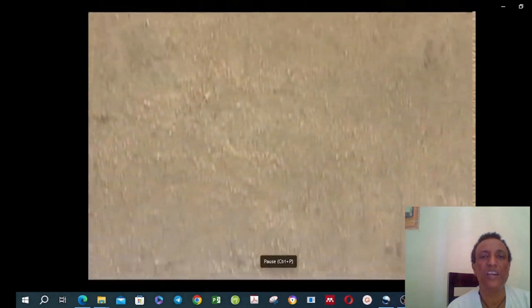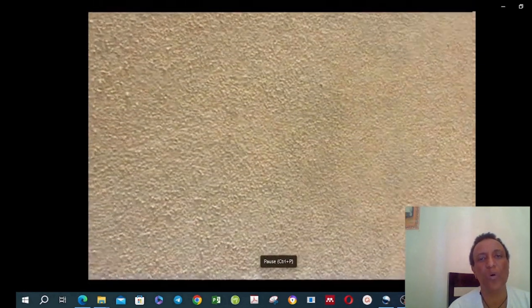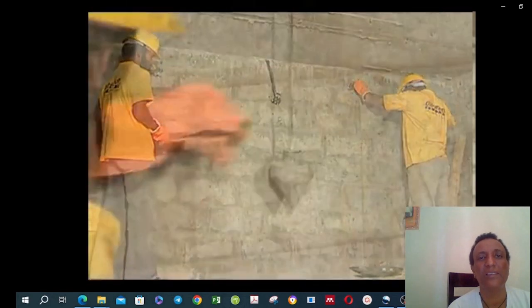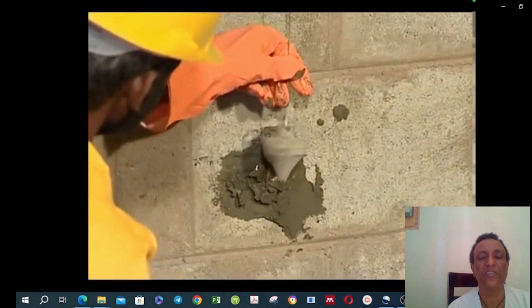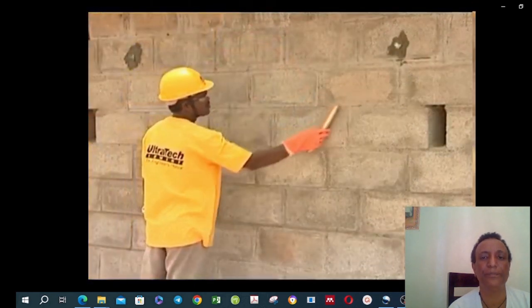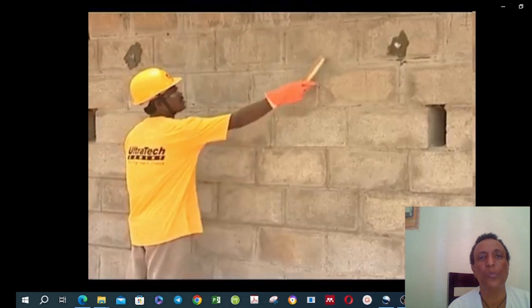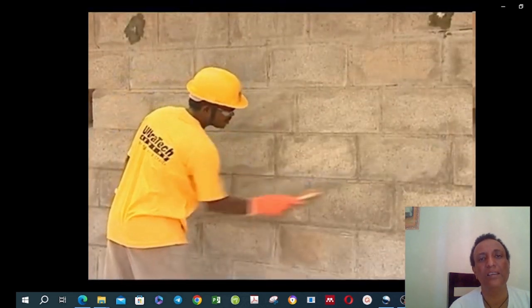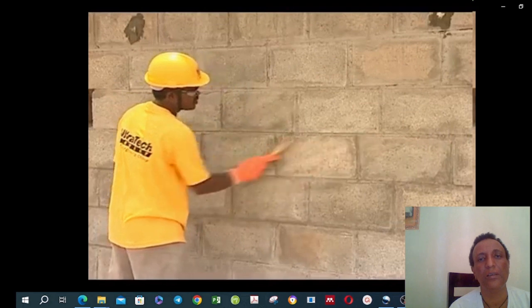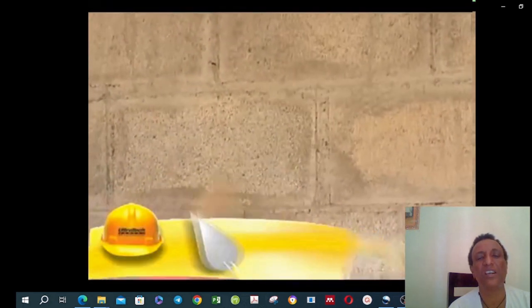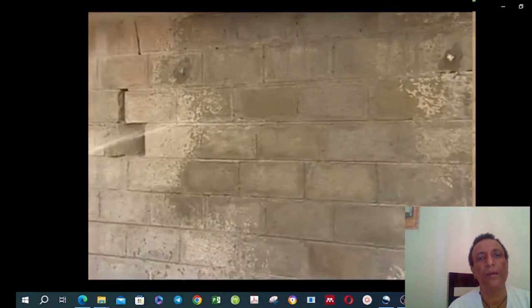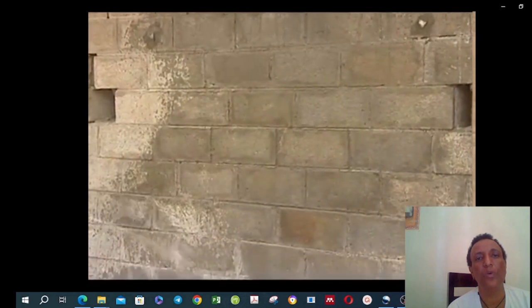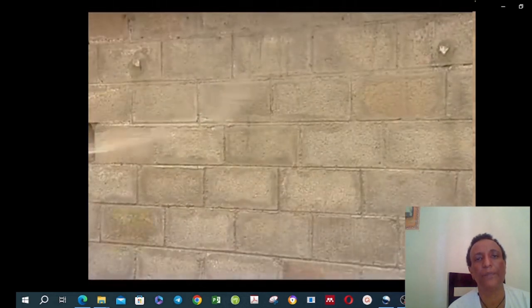This video demonstrates the step-by-step process of plastering. Create reference point or dot to ensure the plastered surface remains true vertical. The surface should be free from any dirt, dust, and oil. The goal is to establish a strong bond between the surface and the mortar. The surface will be moisturized by using water.